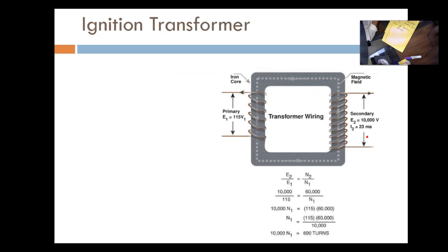Transformers are still being used for a lot of burners like Becketts and Carlins. It depends. I personally find them very reliable, but some burners like Riellos actually have igniters, which are electronic, and they work in DC and they do the job perfectly. So it depends on the strategy and the way they want to produce the ignition.